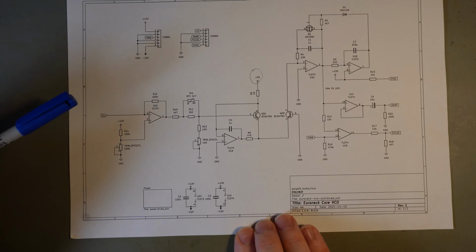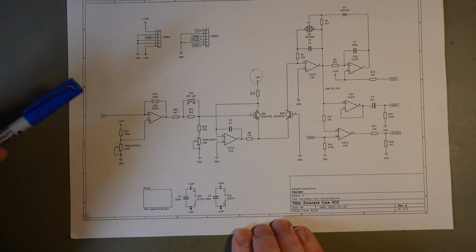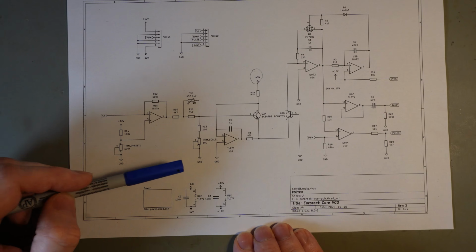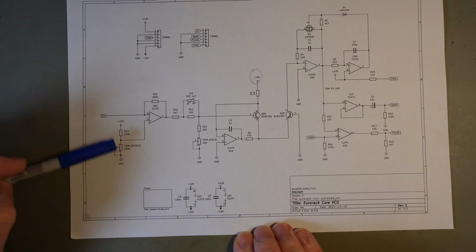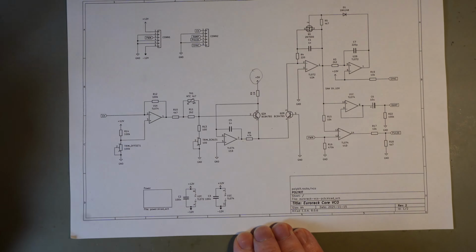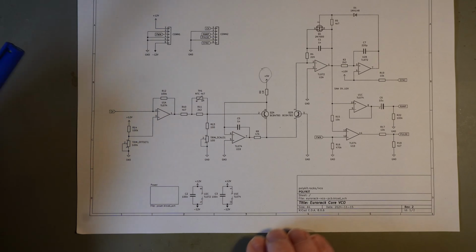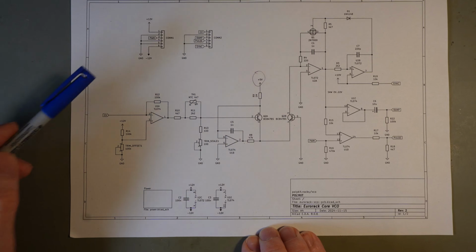What makes the whole tuning process of this oscillator a bit cumbersome is that when you change scale, also the offset moves around. So there's a bit of fiddling involved to get this in tune, but if you're a bit patient, then this will work out.